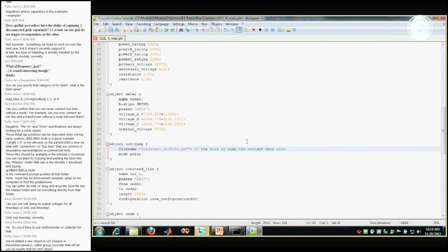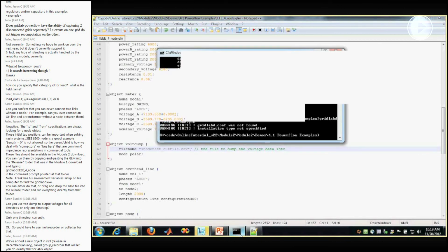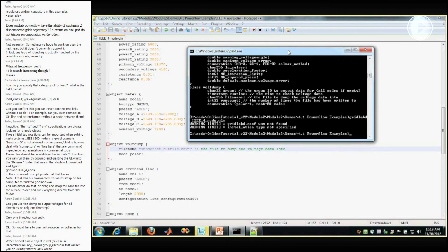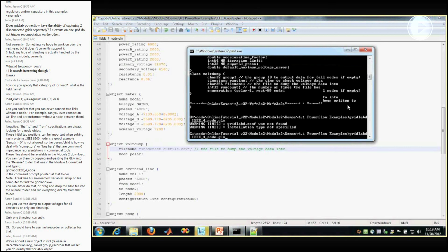This is an issue with volt dump, and more specifically GridLAB-D in general. If you specify the class inside the group selector, it doesn't seem to quite work right. It works if you do a group ID. So if we went in and did a group ID and put it on like node 1 and node 2, we could still use that group field, but for the particular case I was looking for, I guess it does not quite work right.